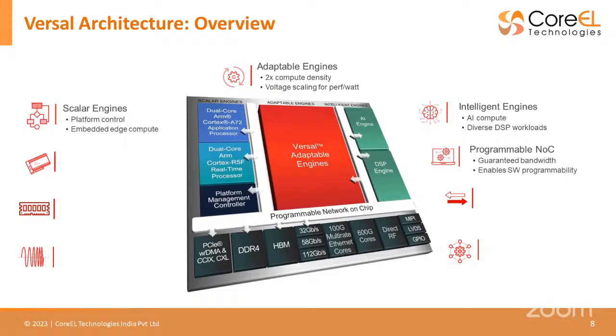So instead of going for a one-and-done solution, you're trying to specify specific tasks. You are going to split those tasks for different units to work on, right? So your AI engines will be dumping the additional loads onto the DSP engines, and your DSP engines and AI engines together, if some kind of faster computation is required, can dump it onto the FPGA.